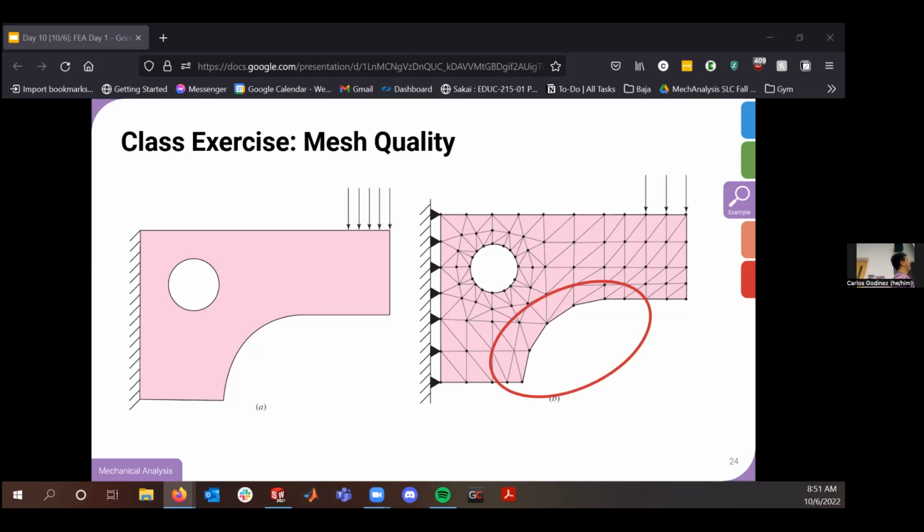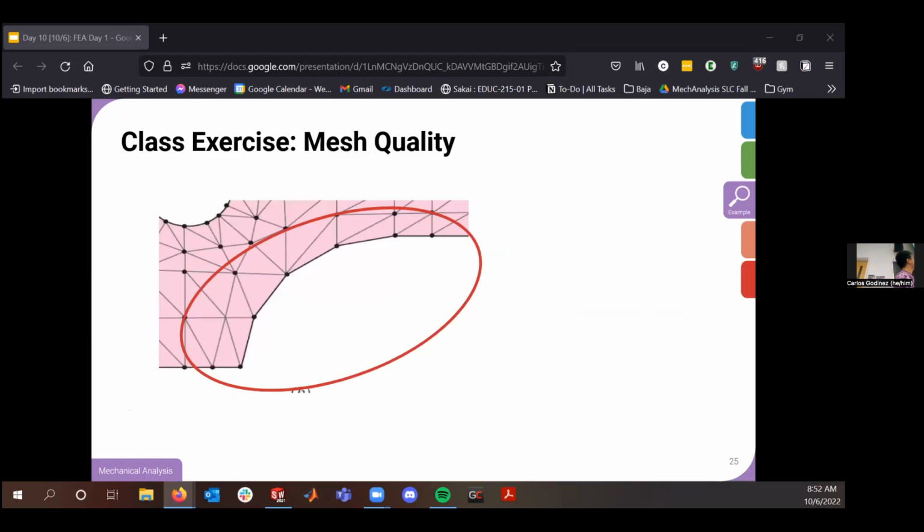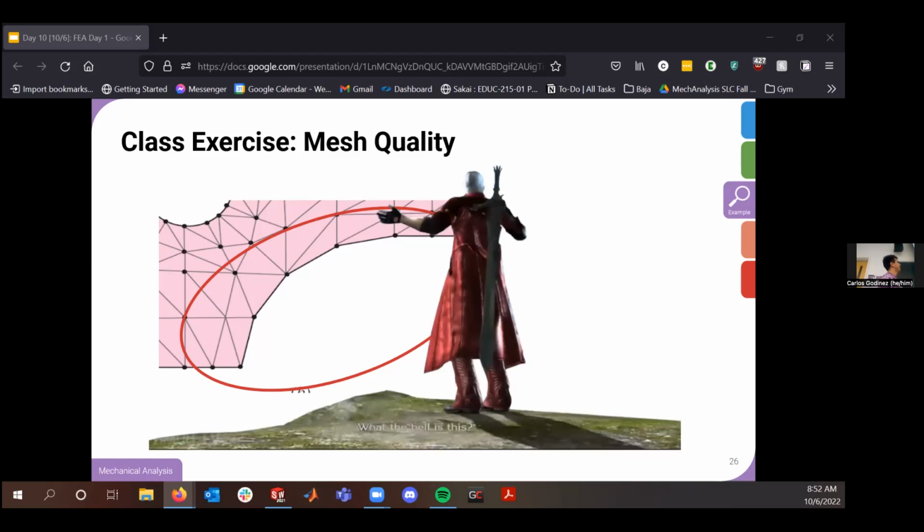So if I pop up right in there, okay? Daniel's exactly correct. If we pull that and blow it up a little bit, you'll notice this fillet has really jagged curved edges that are unlikely to give us a realistic approximation of what's going to happen at that fillet once we deform it.